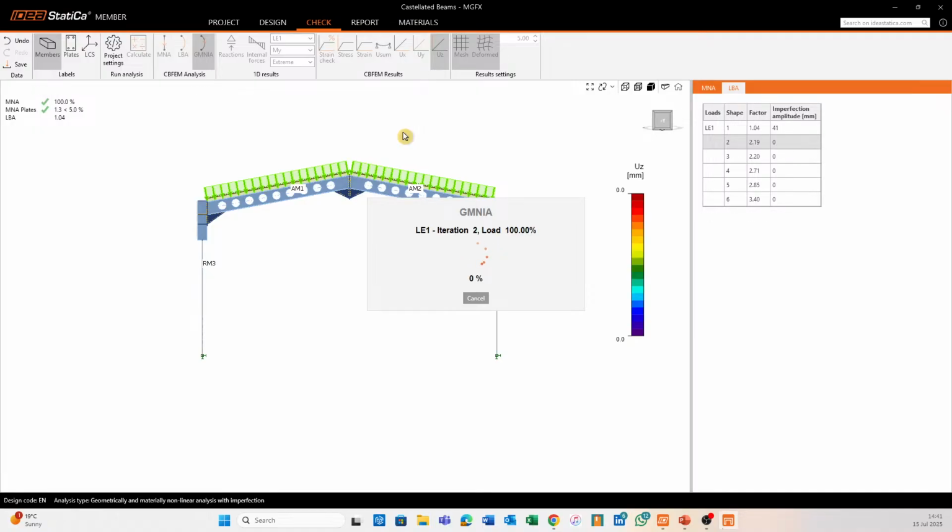So buckling is a really technical topic. Torsion and lateral torsional buckling are not the same thing, and it really takes diving into these things to understand them well. I do not blame engineers for designing torsion out of their models. So basically your geometric arrangement is such that you don't have torsion in your members, which I would highly recommend.